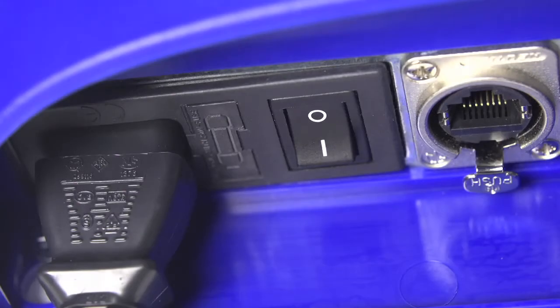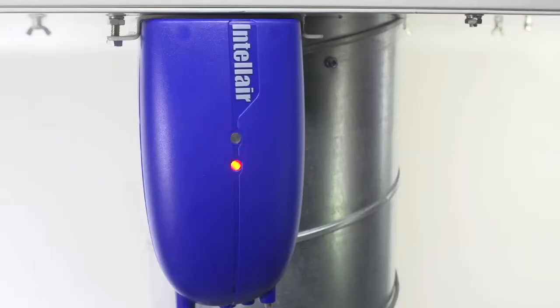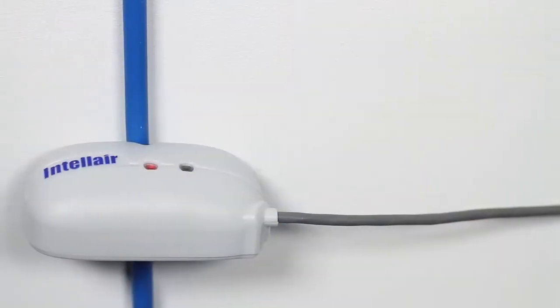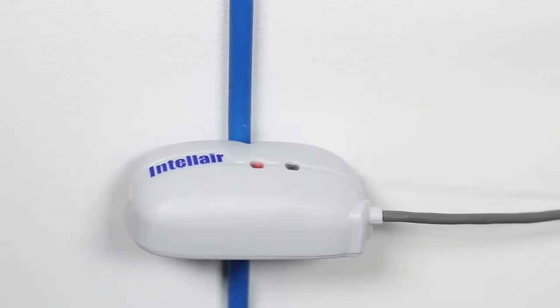Before accessing the configuration portal, turn on the main control unit and allow 2 minutes for the system to initialize. The damper control units, DCUs, should show 2 visible LEDs, one solid red and one flashing red, to indicate the units have power. If a current sensing switch is fitted, one solid red LED will indicate the unit is receiving power.